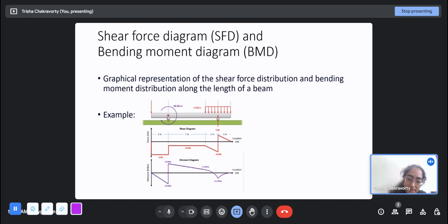To a structure, both are the same. Similarly, a fixed support gives a moment restriction to the structure, right? So a structure will not distinguish between an applied moment and a reaction moment given by the cantilever end. And when there are distributed forces, there tend to be linear lines in the shear force diagram.